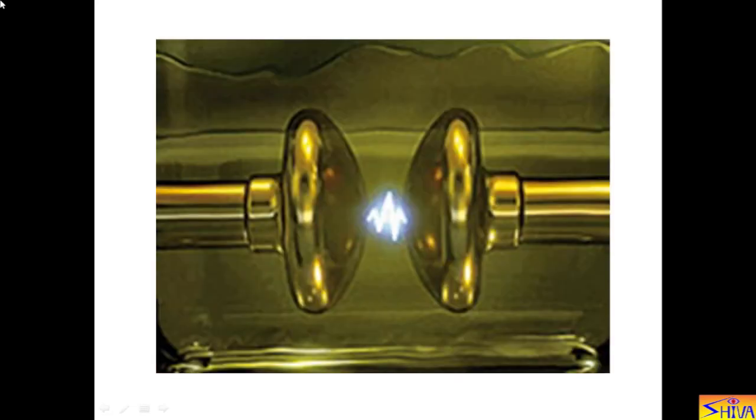So after this type of flashover, we can reuse the insulator because it is in the air, not in the insulator. This is the oil chamber. Two electrodes are there. There is spark between two electrodes. So this is spark over voltage, and after the spark is over, we can reuse the oil. So it is also self-restoring insulation.